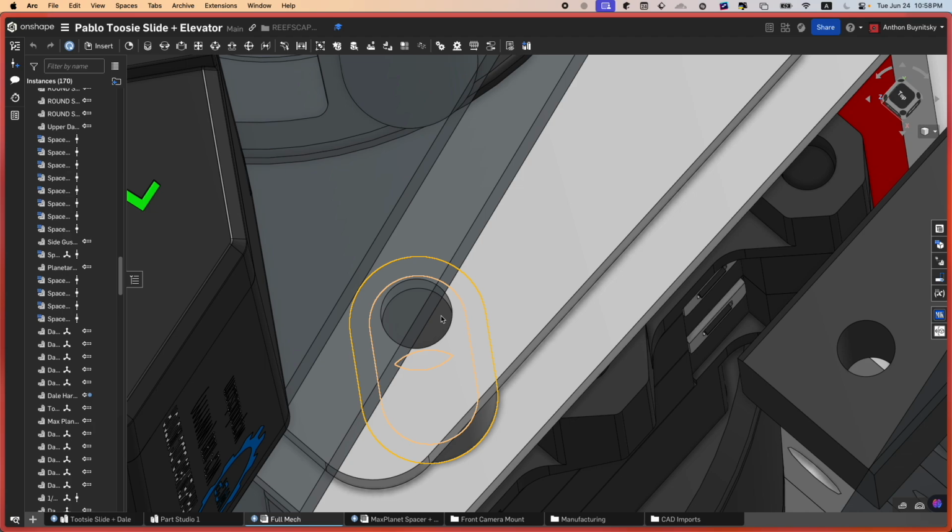So when you put down a layer, the old layer of plastic is going to contract a little bit, and for holes, it'll make them smaller. So when you add tolerance, you purposely design it slightly larger to account for that play. For metal parts, it again depends on how you're manufacturing it.